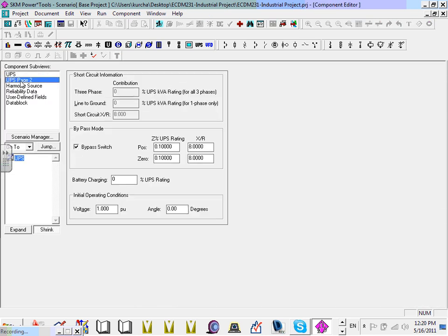I have 4 fatal errors for stuff that's in there that says it's not in there, so I'm probably not gonna. They're not there. Cable impedance not defined. Did you say which cable? Cable, bus duct 208, cable impedance not defined. Okay, go click on it, edit error. Okay. What do you see?